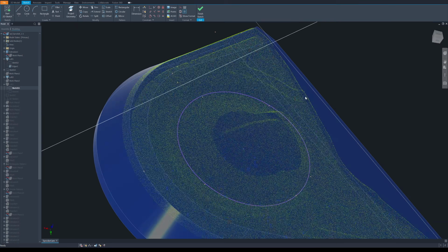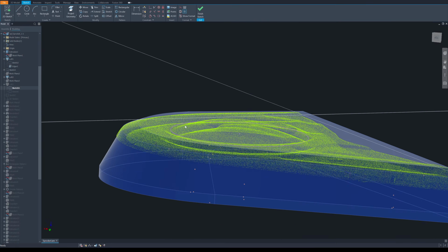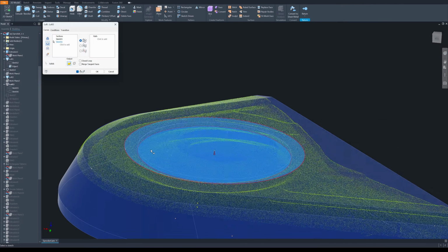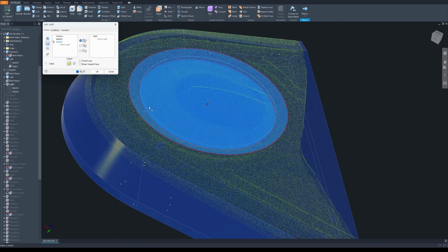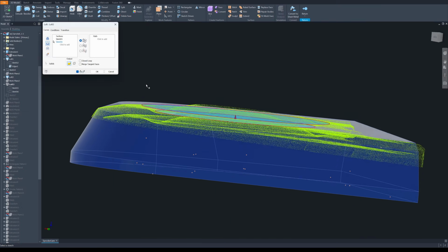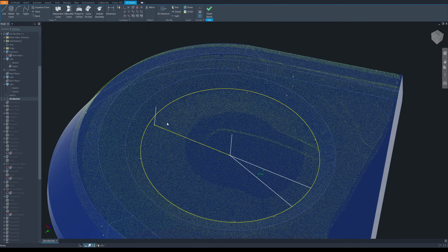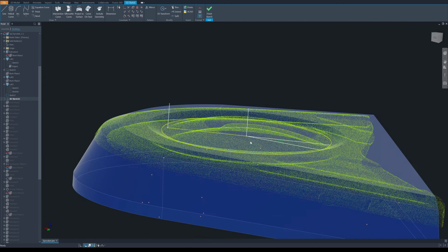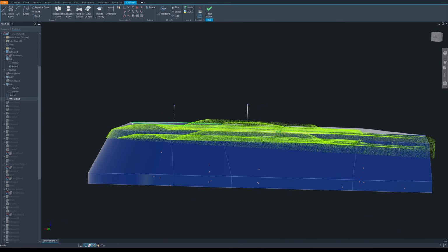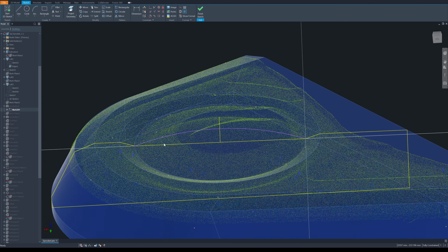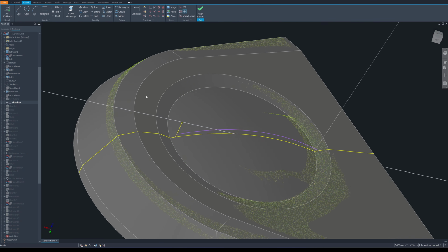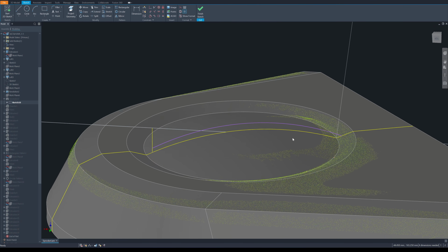Okay, next I'm going to create this sphere dome here. So now I loft cut it with the two sketches, so it will create a circular chamfer pocket. Next step, I create a 2D and 3D sketch for making a revolving axis. Because this plane is not level, I create a sketch for making a sphere. Okay, here's my first revolve. Create a new sketch here for the second revolve.